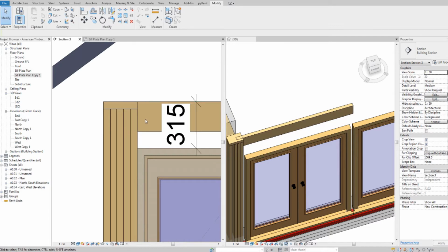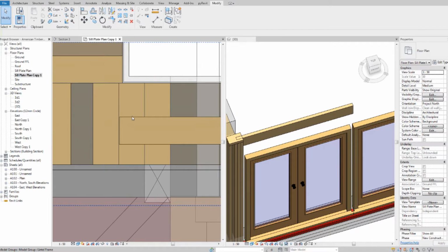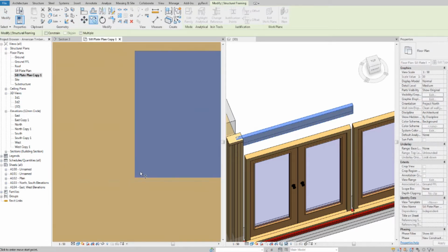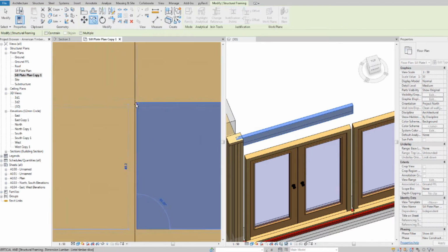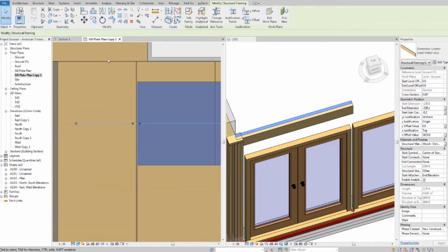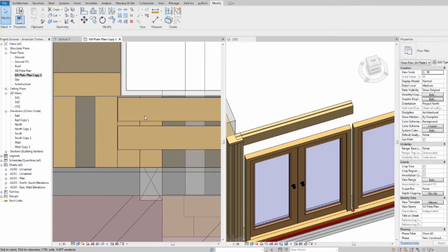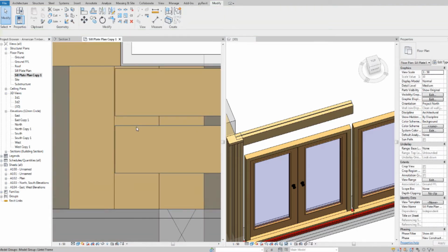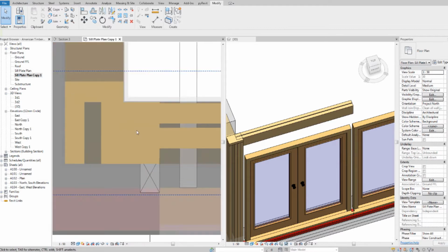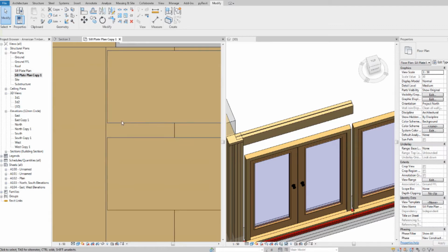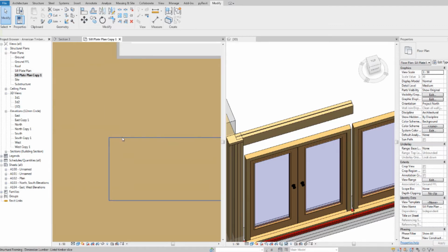Okay, now I'm gonna go back in the section plan and make a copy of this. Drop it here and move it back by 10mm. Right, now I'm gonna put a steel here. I could do it the easy way or the hard way. Easy way, I can just copy this down here, change its dimensions and change its materials.